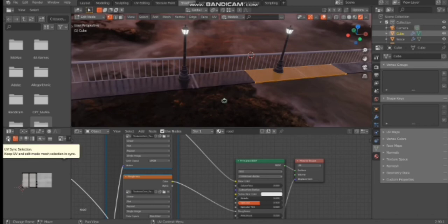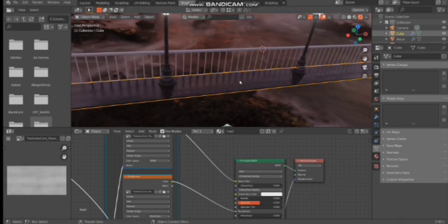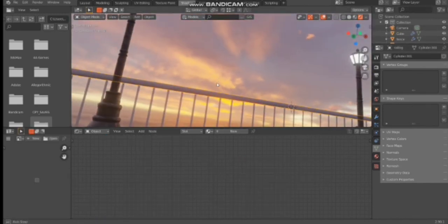and from here we are going to tap to go to edit mode and then turn on shrink selection. Now press R then 90 to rotate 90 degrees and bring it a little bit on the x-axis. Now as you can see, the material is nicely applied. Then we are going back to the camera view.